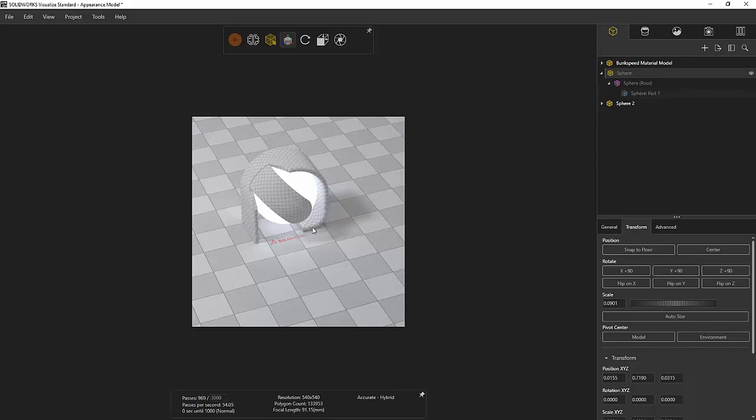Although if you do have the Pro capability, one of the nice things that they have in there is when you right-click and you enter the light, you can tell it exactly where you want to see the light in your model. What that does is back trace that light to exactly where it has to be positioned. So the downside of what I did here is if I need to manipulate the light, I have to do it manually.